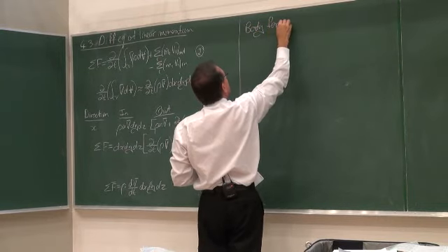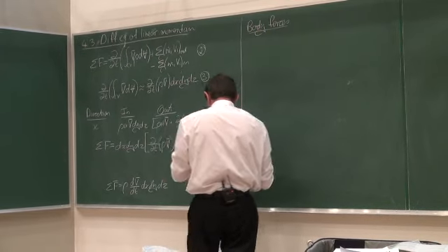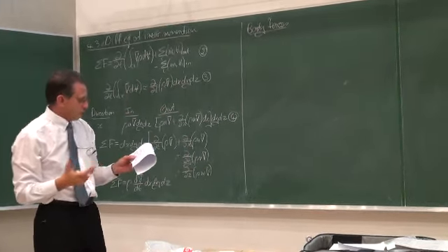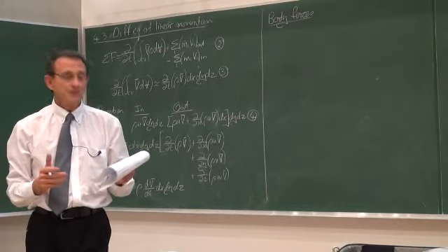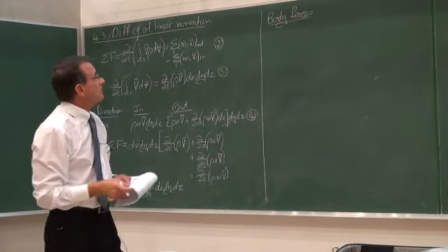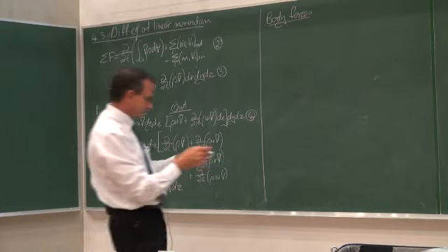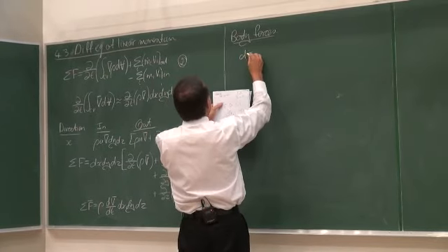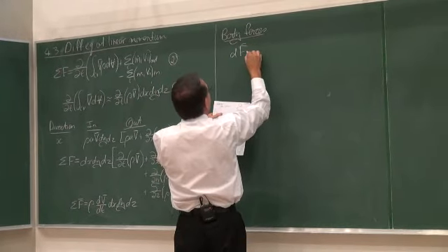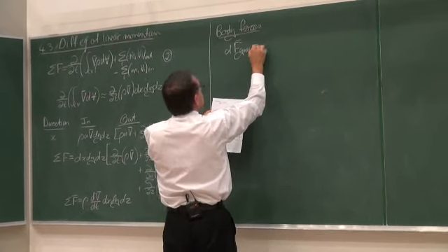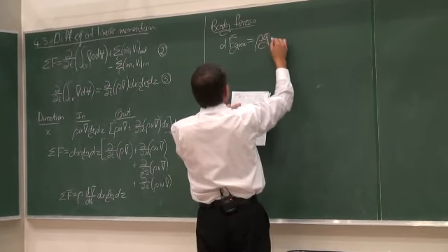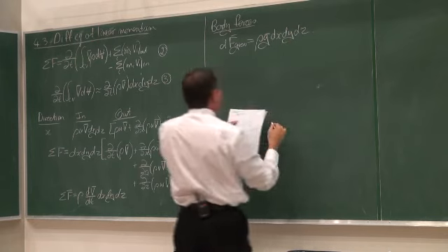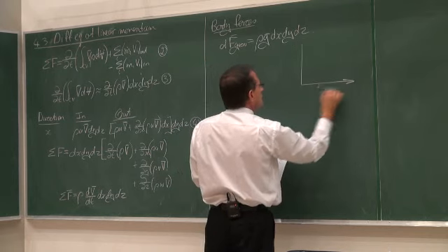Now, the body forces that we as mechanical engineers are interested in is usually gravity, but there are other types of external body forces like magnetism or electrical potential, so they can also be used. And for us as mechanical engineers, usually we would say that the gravity force is equal to rho multiplied by g dx dy dz.